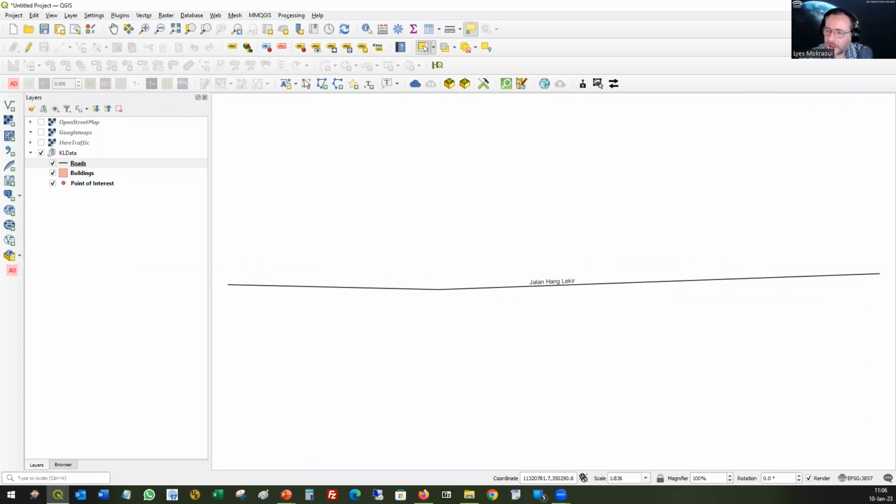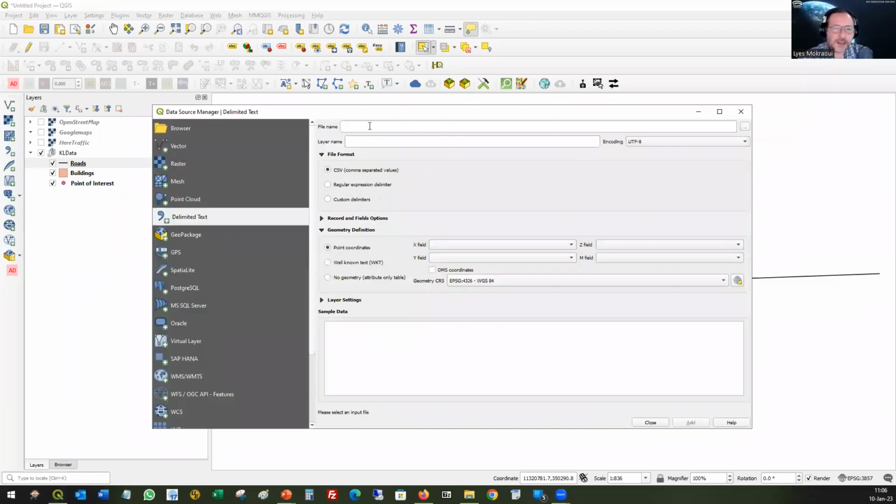Okay, Wimpy TA, all right. If I have tabular data such as a table from fields or GPS coordinates, how do I put it in and process it in QGIS? To do that, you click on this button, vectors, and then you can just add the file name, let's say CSV.